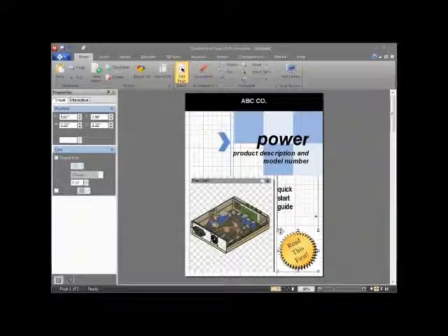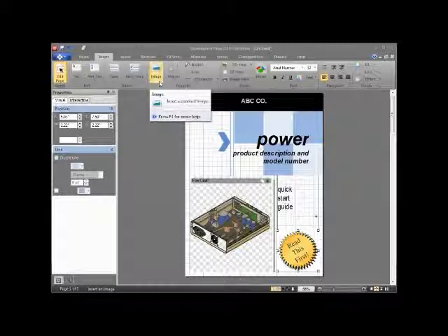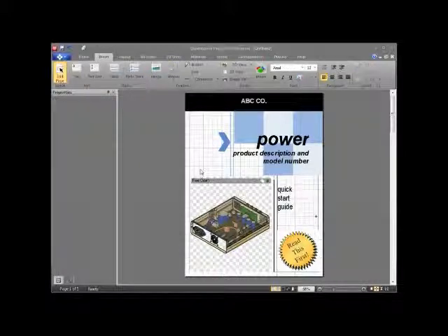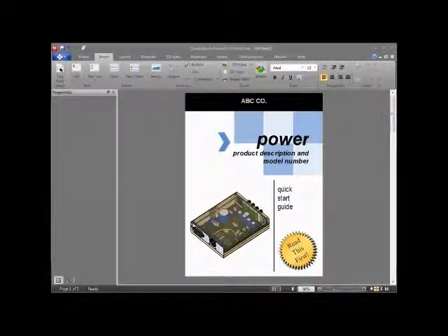This is just an image, and then you can resize it and position it as needed on your document page. If you want to insert any of your own custom images, there's an image button right here that inserts a standard image. That's how you would do a logo. A lot of times instructions have imagery that helps as well as the 3D process. And just like in the other example, you can double click and get into the mode where you can actually orient your 3D model. So let's just set up an orientation there. We're done with our first page.